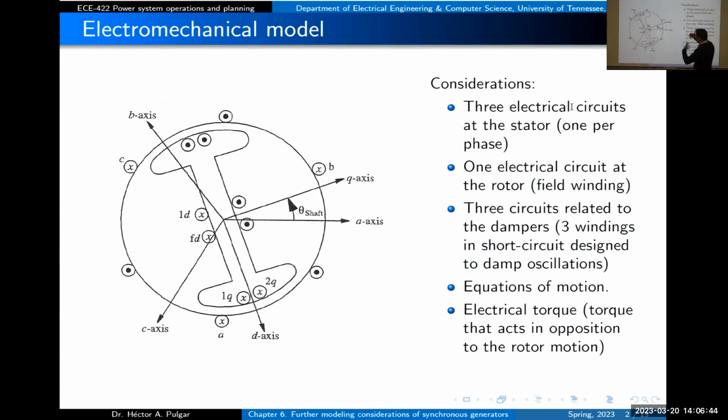So we start again from this figure. That's going to be the physical description of our machine. We will have the stator, in which you have windings that are stationary, phase C. This is a two-pole machine. So in the rotor, you see, we will have just a flux going in one direction down here. Here is going to be the north magnetic pole, and here the south. So the flux will come out of here, and through the stator will return on that side.